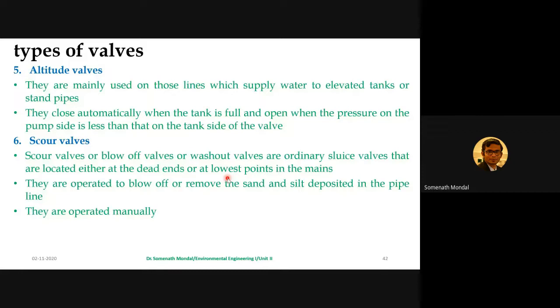Mostly for the elevated tanks and the stand pipes. These are the two components before which we attach the altitude valves. The reason why these altitude valves are required is that they close automatically when the tank is full, number one, and open when the pressure on the pump side is less than that on the tank side of the valve. Fine.